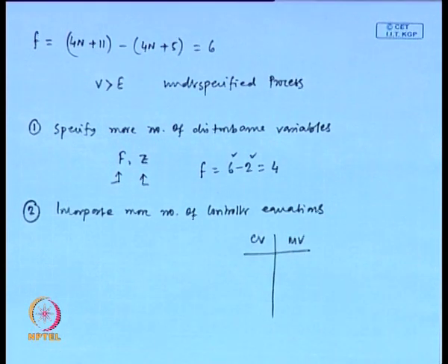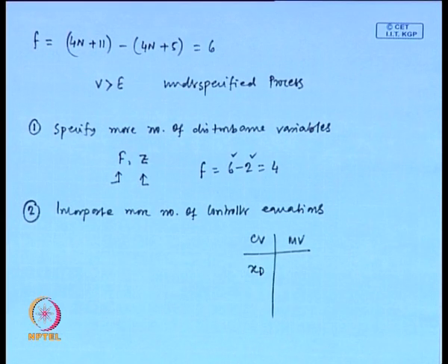See, this is a distillation example. Feed is introduced on a particular tray. We are getting two products. One is the top product, another one is the bottom product. So, what is the control objective for this process? Control objective is to maintain the product compositions, product purity. Fine. That means we can consider one control variable as top product purity, which is represented by top product composition.